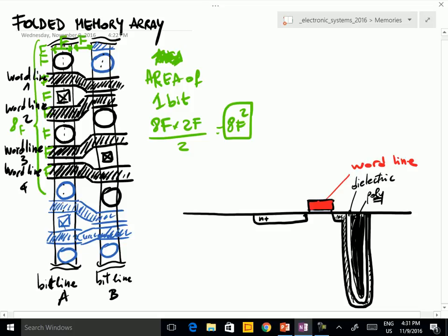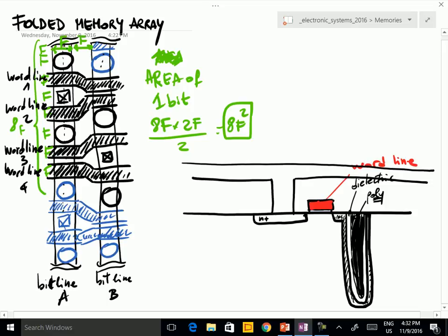So in order to obtain the capacitance and to have a large area for the capacitance, we obtain the area by drilling a hole below the transistor. So from the top you see something like a circular footprint. Okay, here we have the contact with the bit line, which passes above everything. So this is again an insulating layer, insulator, and this is the bit line.